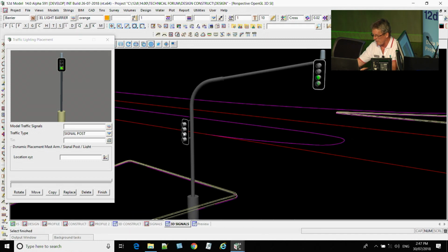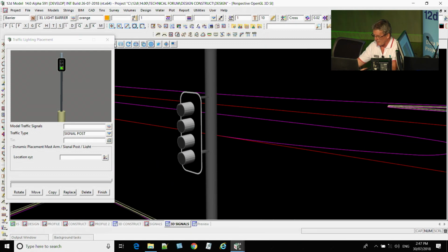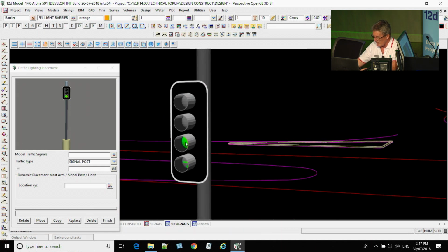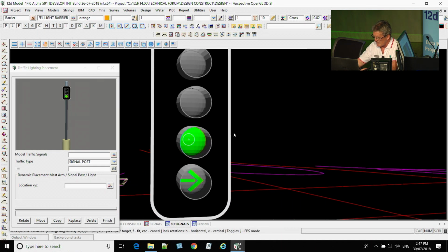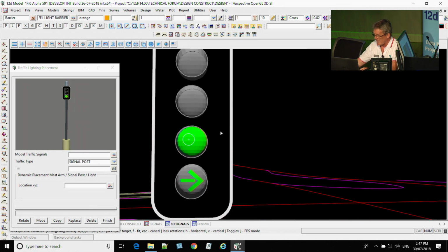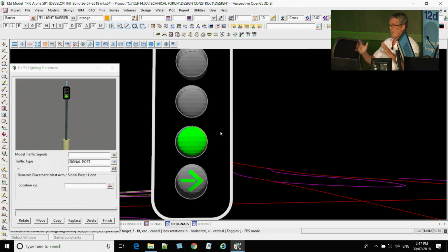This is what I talked about before, about having to do the little LED, that little guy in there. I suppose I shouldn't have said Brendan had a lot of time. But that's the thing that was squashed, the actual shape, to make it look like that. 12D had an option there to cut the Trimesh in half. So that's what we did, and then we just changed the factor in the Z direction and flattened it.